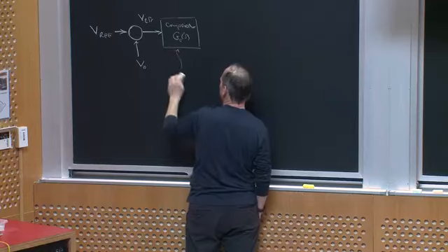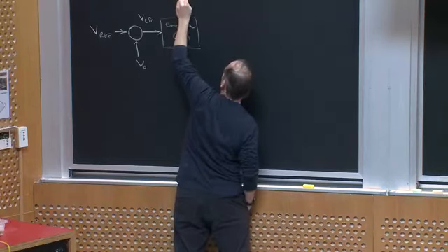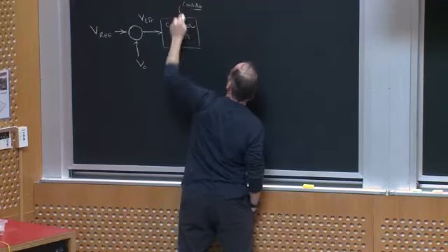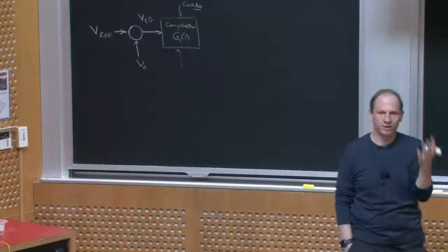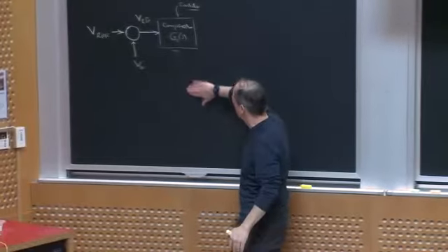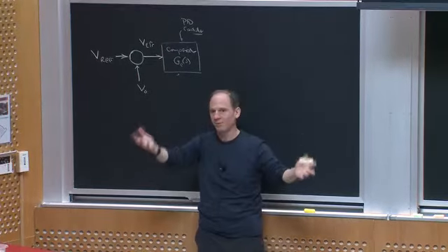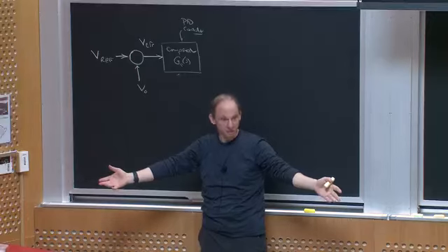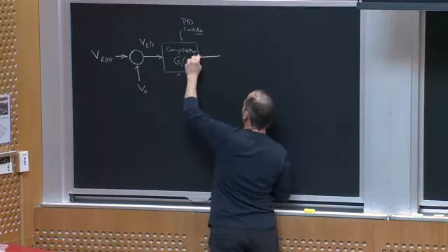This might be, for example, a PID controller or something fancier. Depends on the topology, right? This is where having a control class helps, but you might think what this does is if I have error, I amplify that error by some amount, either proportionally or by looking at the integral of the error or something like that, and generate an output, which I'm going to call VD.